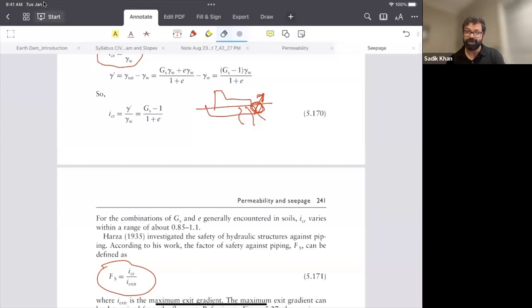So what you need to do here is have some kind of filter layer. The filter layer has big voids inside, so water comes in and doesn't get the same confinement it used to have. If you take the confinement out, you take the pressure out, because it doesn't get any reaction.